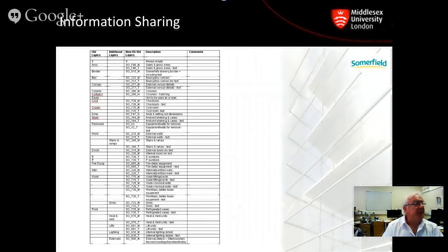Coming up now is how I mapped those things for them onto the BS 1192 format, using a CISFB coding classification for building elements. Yes, there's more of it, of course, but there is a standard, an industry standard, a common understanding there. Look back at the left-hand column: the things they called box, what could that be? Boxes of food, boxes of drinks? No. It was the little bits and pieces left over when a standard shelf unit or refrigeration unit didn't fit exactly between two walls. A length of cabinets didn't fit, and they just boxed it in. They filled it in, and it was all those little infill pieces that they meant by box. But there's a classification for it. It can be done. It's dead easy, a half-hour exercise to map that onto BS 1192.